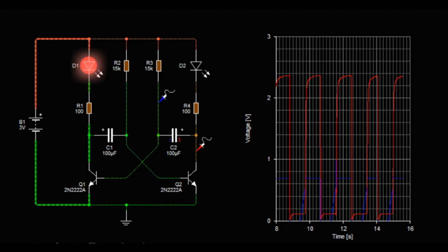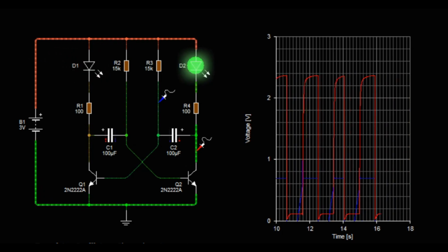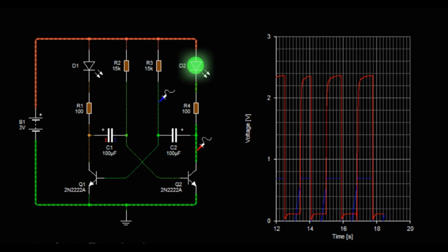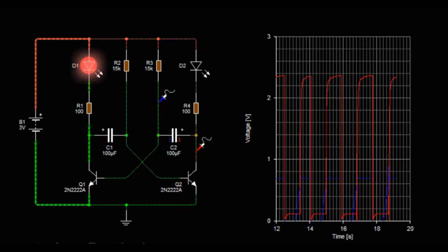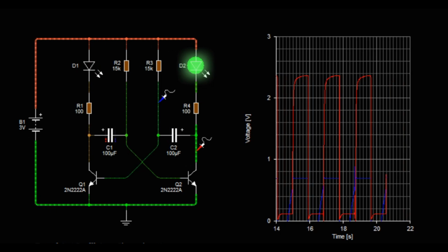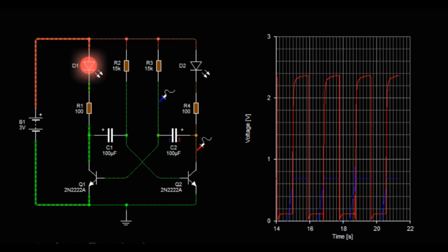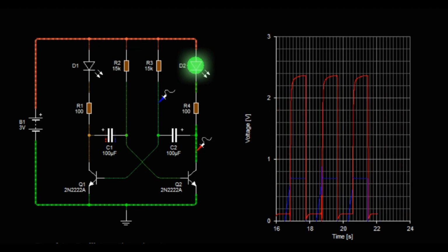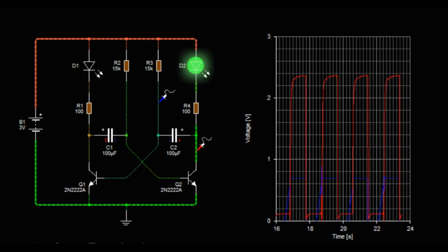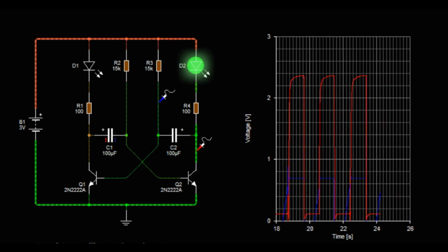Components you'll need: 2 NPN transistors, for example 2N3904 or BC547, 2 capacitors, C1 and C2, typically electrolytic capacitors, 4 resistors, R1, R2, R3, and R4, and a power supply voltage, VCC. Here's a step-by-step explanation of how the circuit works.